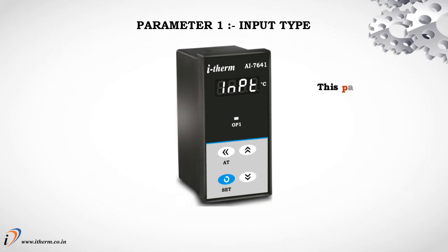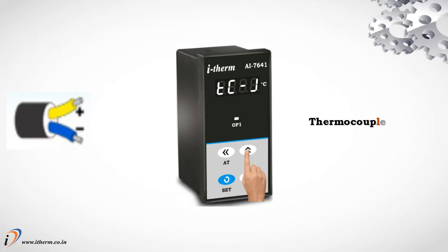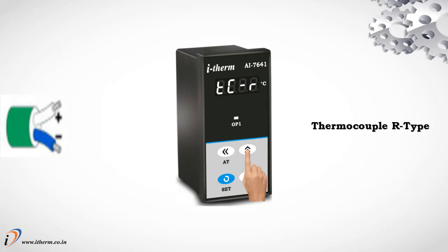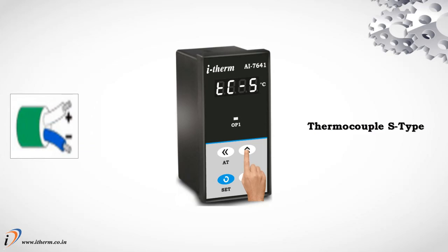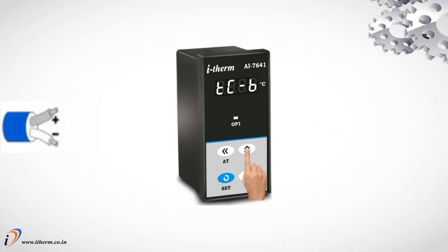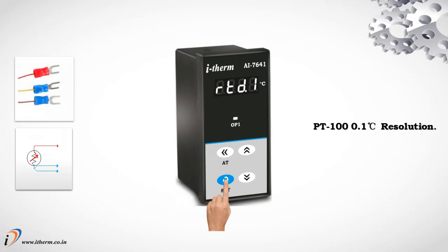Parameter 1, input type. This parameter value is set according to the connected sensor type. Thermocouple J type, thermocouple K type, thermocouple R type, thermocouple S type, thermocouple N type, thermocouple T type, thermocouple B type, PT 100 with 1 degree centigrade resolution, PT 100 with 0.1 degree centigrade resolution.